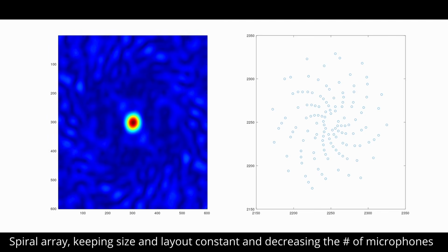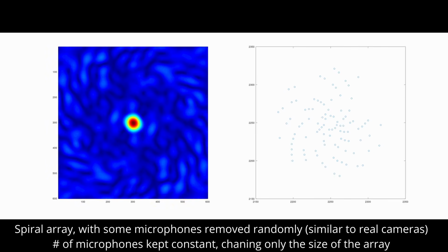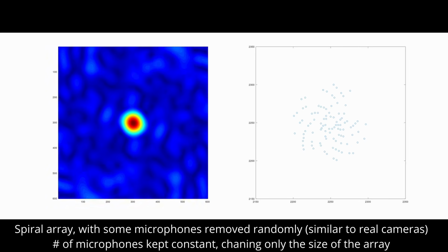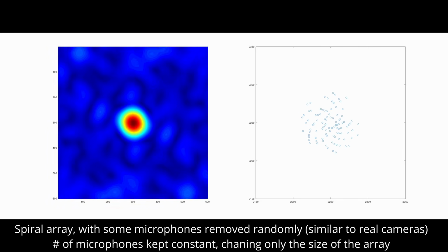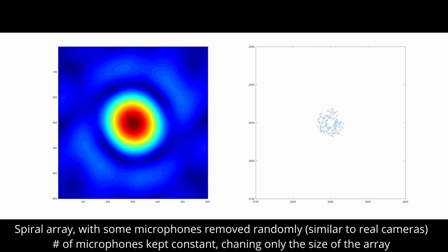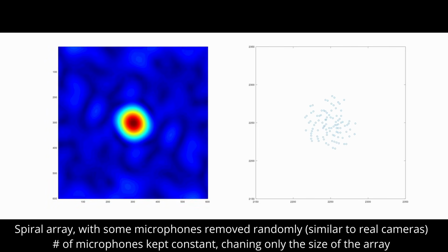So having fewer microphones, 64 in this case, means that the best possible contrast we can have in an image is 64:1. Exactly which microphones are populated again could probably be mathematically derived, but practically it's better to do a combination of simulation and real-world testing. And when I talked with the engineer at Fotric, he said that's exactly how they did it here.